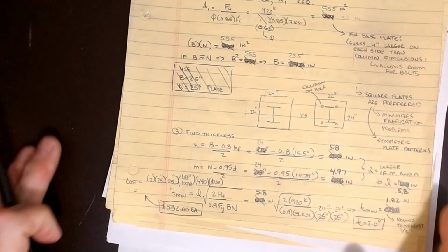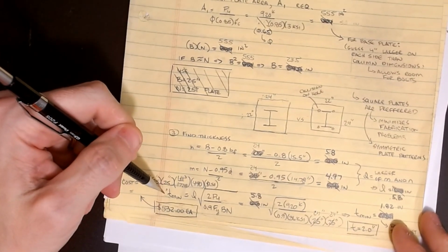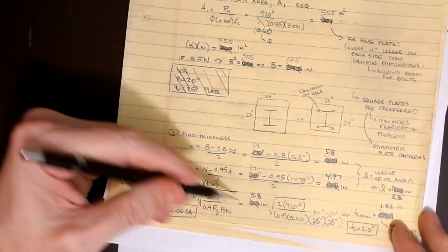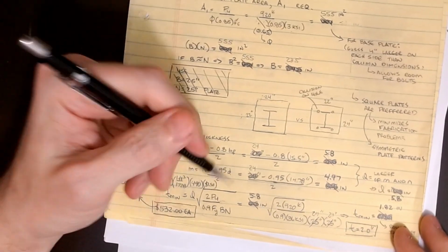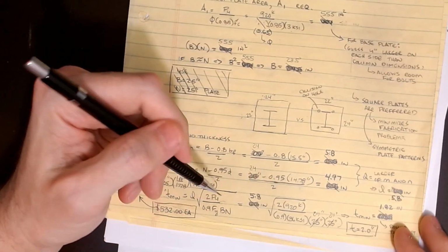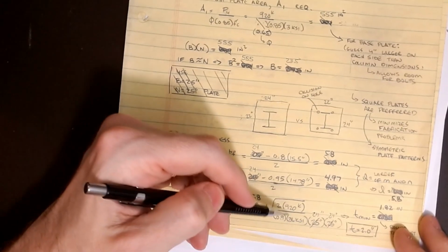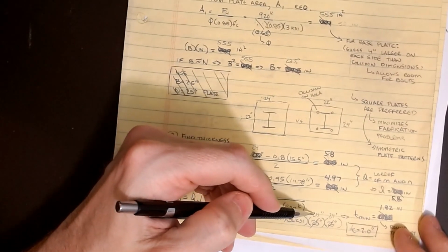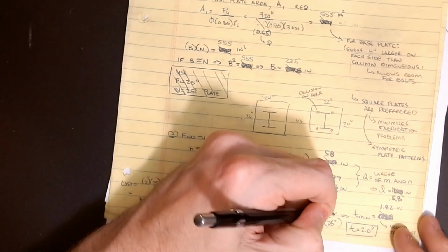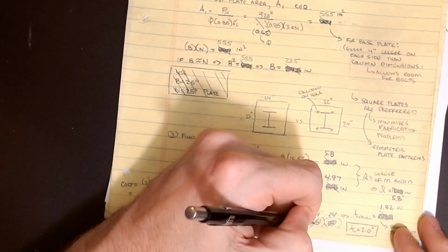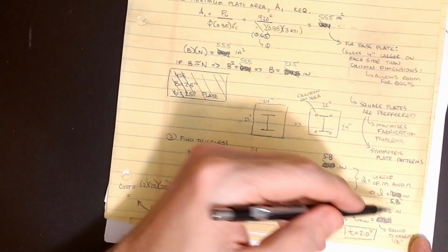If you look at what we have happening there, once I have that, then I can jump down and I can calculate the thickness using my formula here. You know everything now. So this L parameter is 5.8, and then I do the square root of 2 times Pu. So that's 2 times 920, all over 0.9, all over 36 ksi, all over 24. So again, we're doing 24s here, not 25s on this. Okay, and so when I do that, then the t minimum is 1.82 inches.